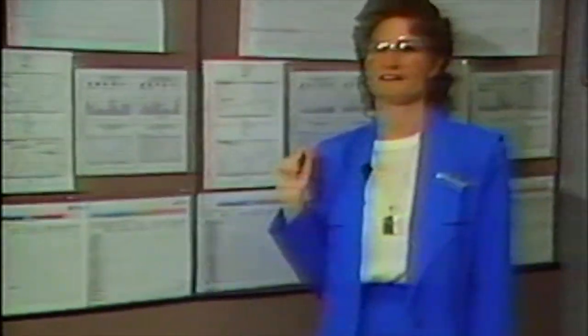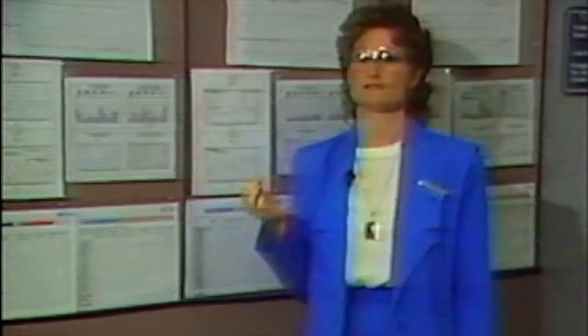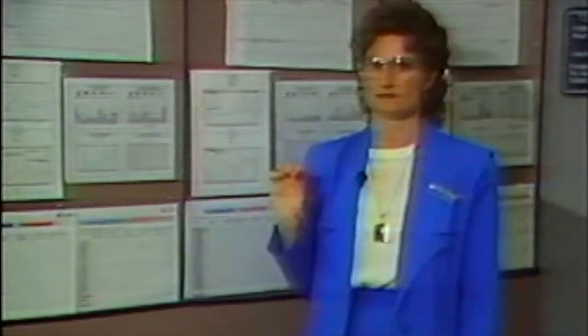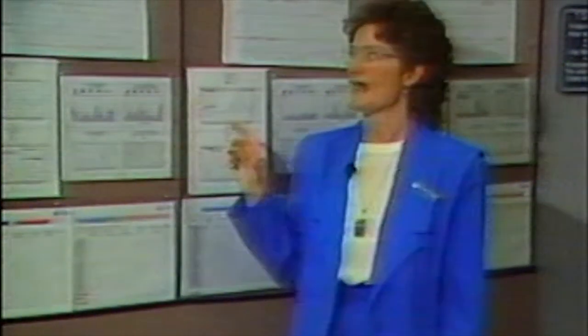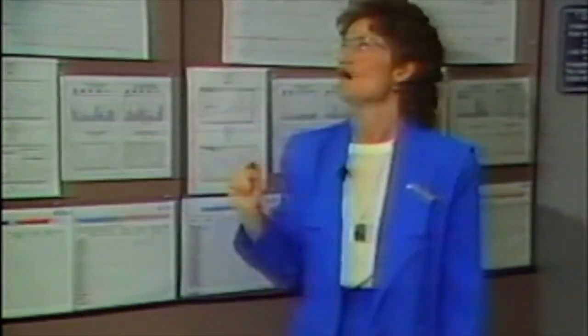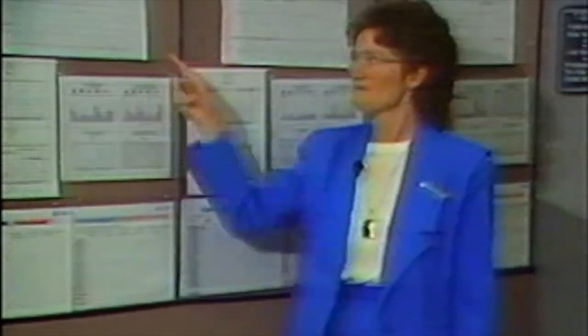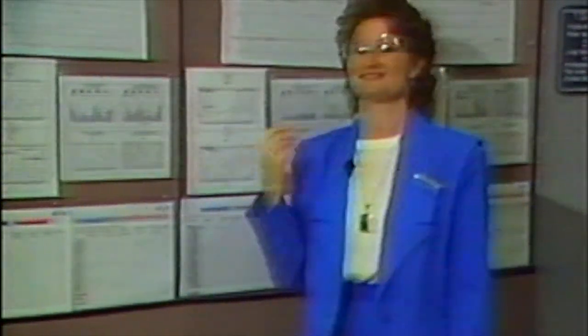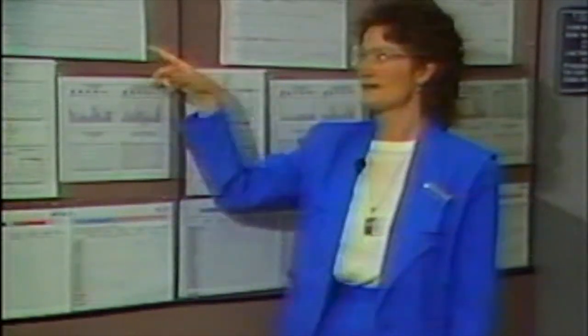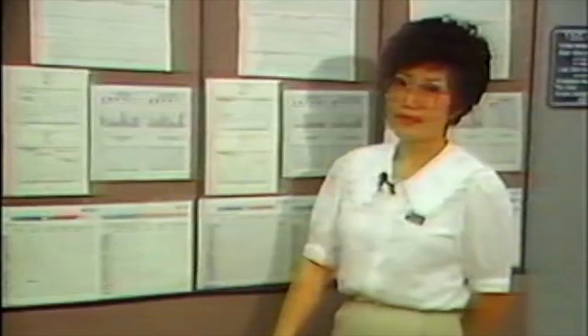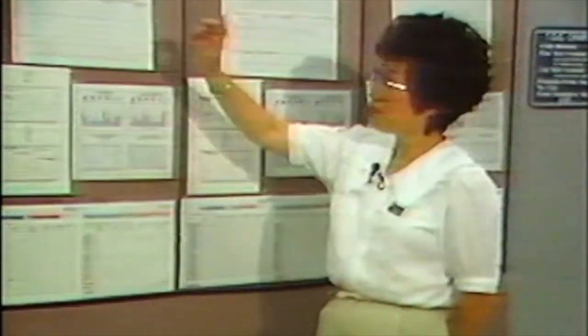This wave solder process in particular has provided us with a real success story with statistical quality control. A few years ago, we had a quality level about 20,000 parts per million in this process. And through using statistical quality control methods, we've been able to achieve an average of 2 parts per million on our wave solder process. But we're not satisfied with that. We continue to work on this process so that we can get it down to 0 parts per million. Now, let's hear from the supervisor in charge of this area.